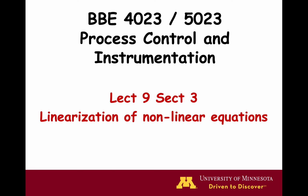In the previous video, we talked about liquid levels in tanks and flow from tanks. You may have noticed that we always assumed laminar flow, so that we could use the equation Q equals Z over R. Well, you may remember from your fluid class that not all fluid flow is laminar. So we need a way to handle nonlaminar flow, which has a nonlinear term. We will also illustrate a nonlinear term for the fluid heater problem, when both the temperature and the fluid flow rate vary with time. This material is covered in section 11 of the course packet.